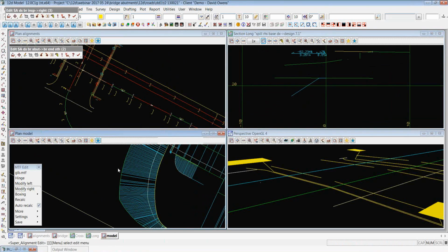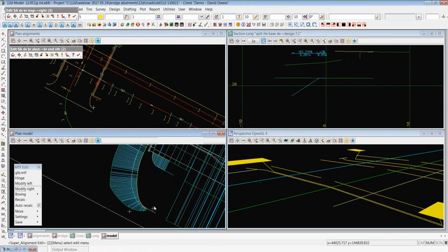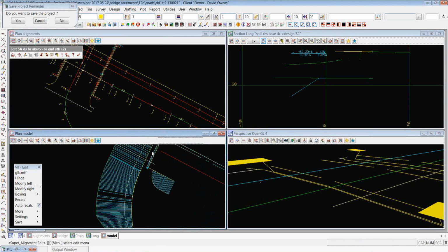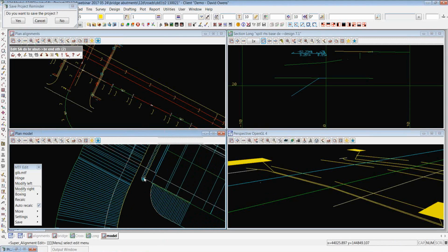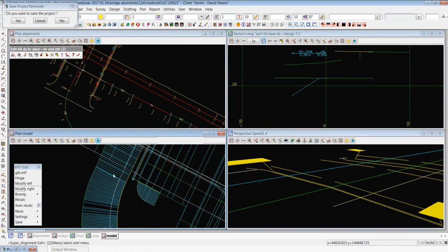Okay? And by having this curved shape and by having some decent segments to hook onto, then I could do the rotation of the crossfall from the 1 in 2, where it's perpendicular to the road, around to the 1 in 1.5 or 1 in 1, whatever you need to do, when it's running parallel to the road or perpendicular to the headstocks. So much easier to do the transition of batter slopes on that sort of shape than on a single point, which I would have to try and do if I did it all from the alignment up the top. So breaking it into 2 made it much, much simpler.